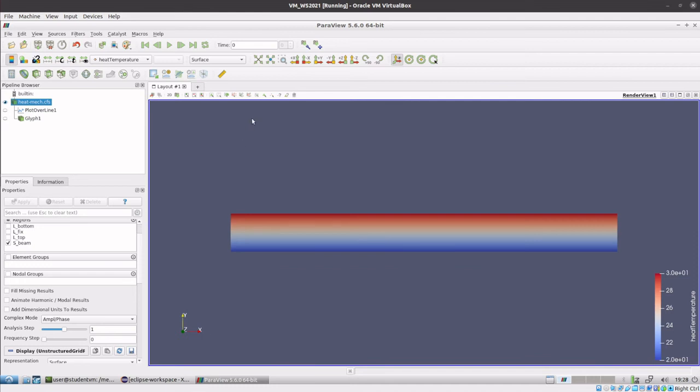In this term, there is a delta T, and this delta T is made up of this temperature distribution minus the reference temperature, which was defined in the material XML file to be 25 degrees centigrade. So here we're having this temperature field minus 25 degrees centigrade, which is the delta T that we are considering in the thermal strain term.